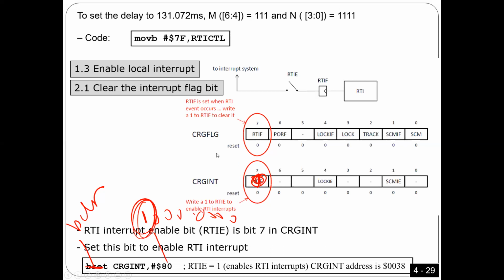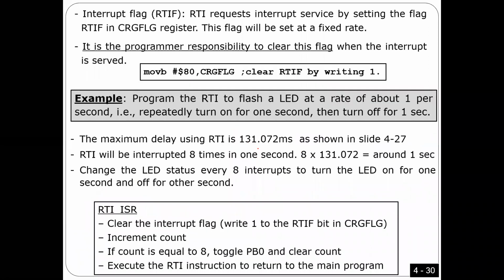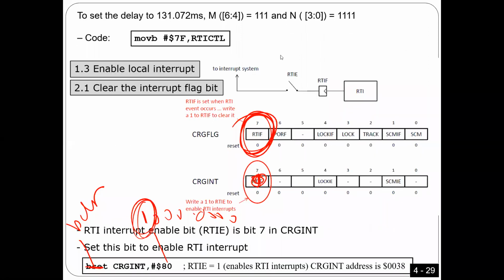The other thing now is the interrupt flag bit. I told you for the interrupt flag bit, the bit here, it's your responsibility to clear this bit. But there is something a little bit weird here. The way you have to clear this bit, guys, is by writing one.